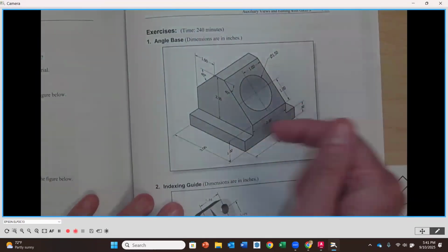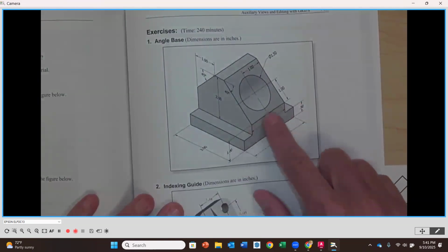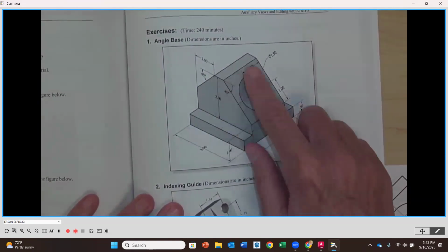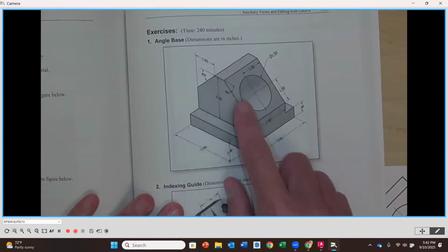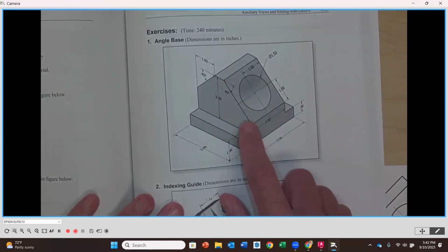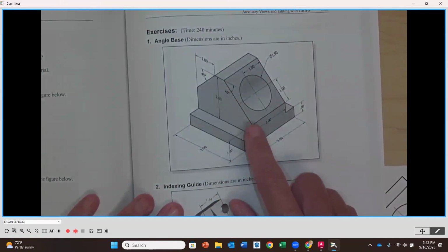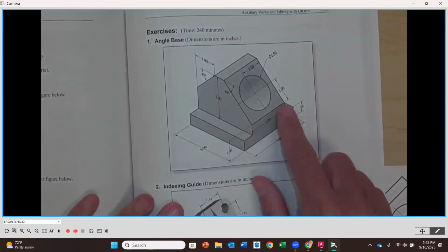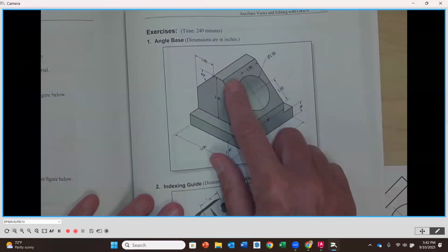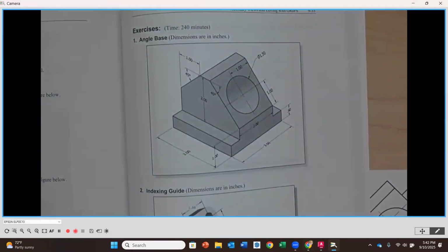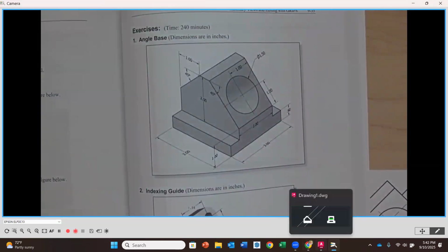So right now we're going to be looking down. We have a construction line for this one, and we have a construction line for this one. Okay. And what we're going to do is draw from one construction line perpendicular to the other, the object line between, and then we're going to draw a 2-inch line along the construction line, then back on the other side, and then we're going to close that loop. Okay. So we're going to go around that perimeter for the true size of that.